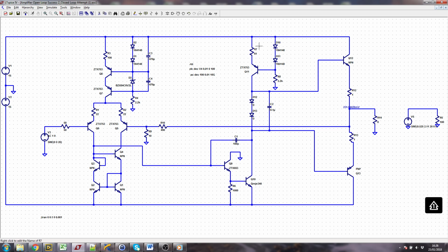I know this source probably works okay. If I look at the current there, it's 11 milliamps. I said it'd be about 10. Fine. This voltage 1.1. This voltage 200. So there's about a volt across there. Probably explains why this current's a bit small. It's quite large actually, 30 milliamps.